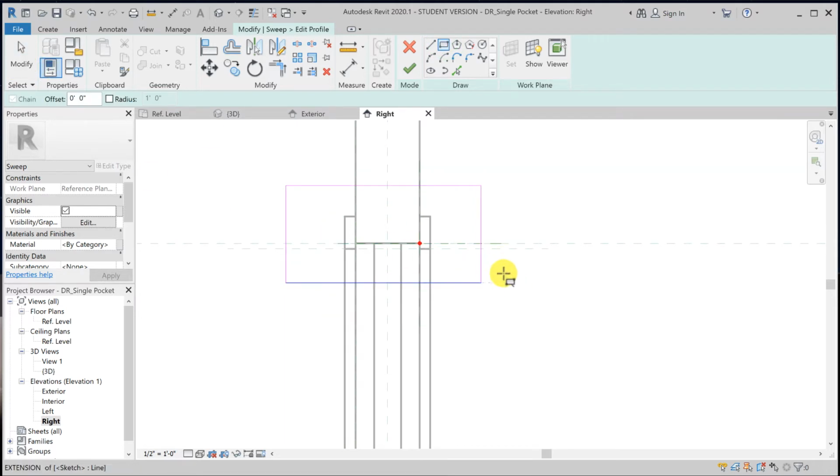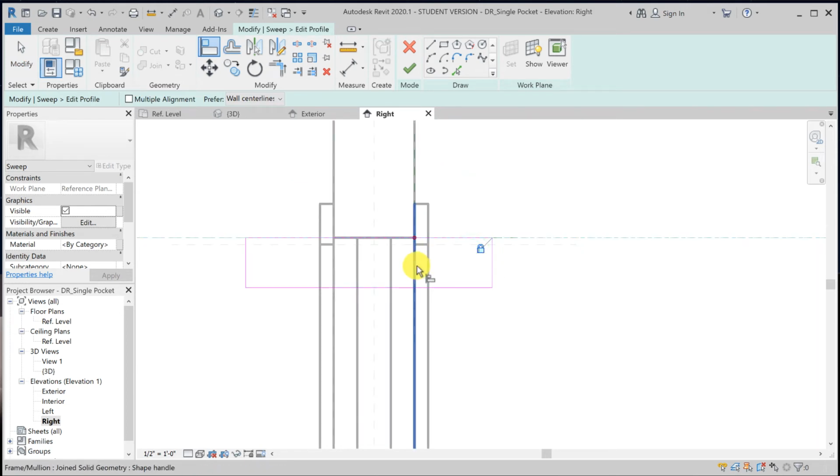Okay, I'm going to lock the top profile. Let me AL. I'm going to lock the top profile with the reference plane that came with the sketch profile. Okay, all right. Let me do that again. AL. Lock it. And then for this one, I'm going to lock it with the reference plane that came also with the profile. So I'm going to tap until I can find it. That's it. That's the one, the shorter one. Okay. And then lock it.